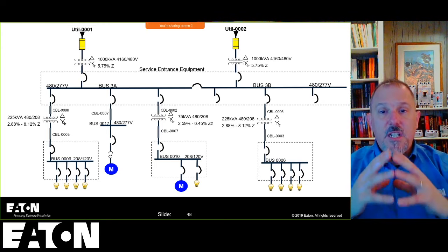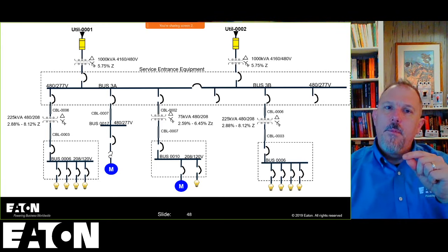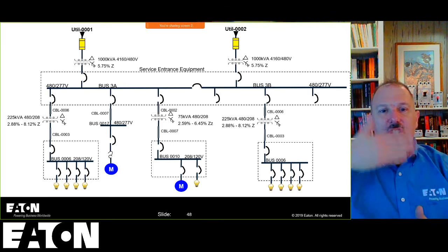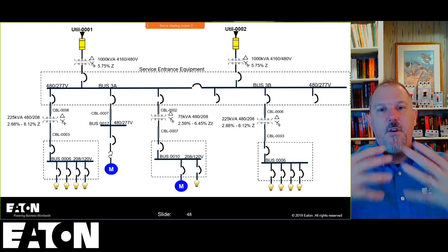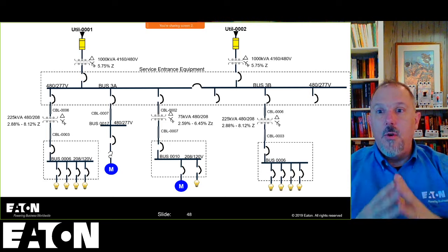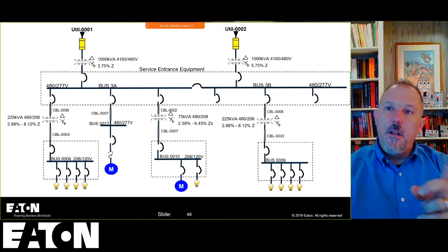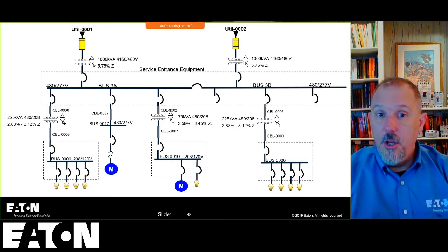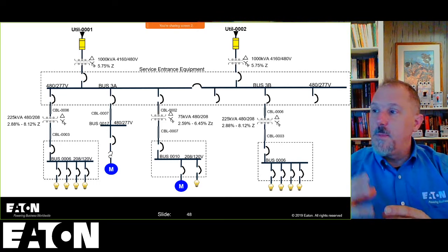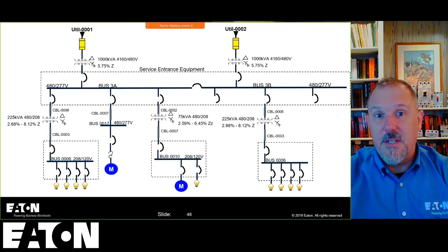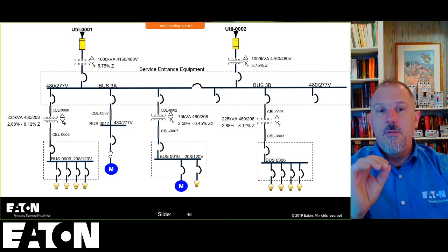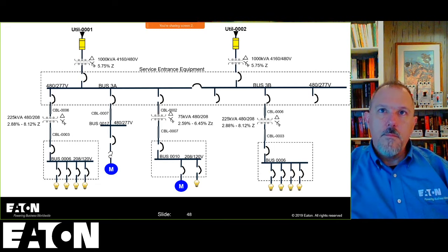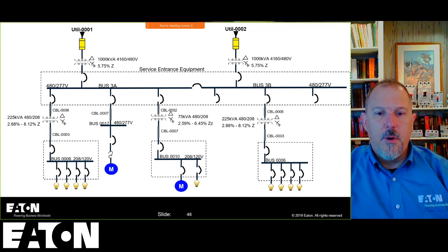Yeah, the variable frequency drives, another good point, which I'm not even sure I covered in my short circuit class. But variable frequency drives give you that shield, right? Because that fault current, that motor contribution, is going away. So you take a facility and you say, I'm going to change all of these out to be driven by variable frequency drives. Now you are reducing the available fault currents because you don't have that motor contribution, although you still have that same size motor there. The VFDs don't push that current back onto the system. They isolate that motor. Good point, Vernon. Very good point. Thanks for chiming in.